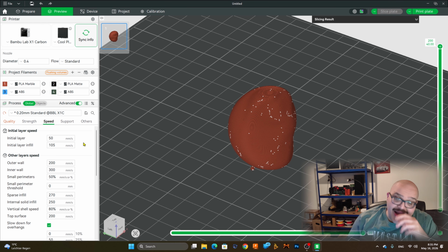Whenever I change speed, I actually change speed more so for the infill rather than the wall. It's because in infill, if you get a little bit of damaged infill or a little bit of nasty looking infill, you don't look at the infill; it's on the inside, and the infill is there to confer weight and structural properties, not so much aesthetics like the wall does, because the wall really plays a big role in the aesthetics of your 3D item.